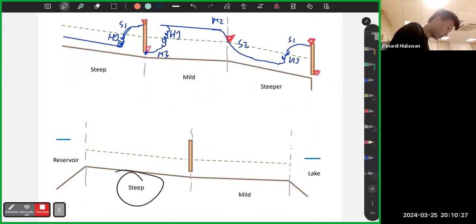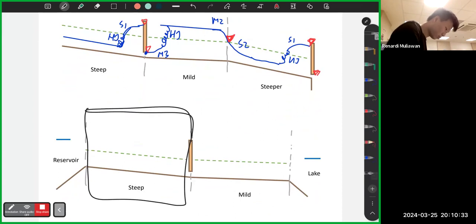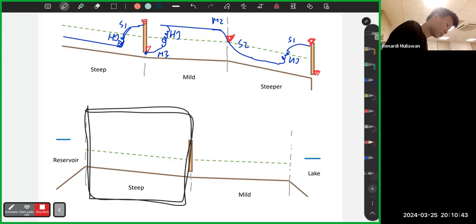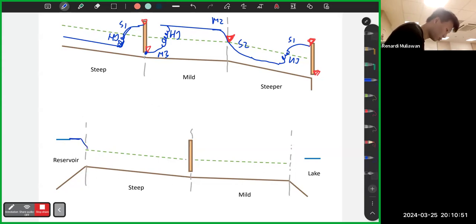Okay, now let's look at this. So steep slope, draw a box as usual. Then for steep slope, it is upstream control. So you care what's happening upstream, and the curve is also upstream of the box. So here. Since it starts up above, there should be a curve going from up to below. So the curve is S2.